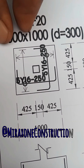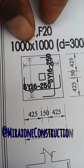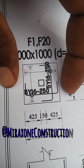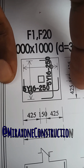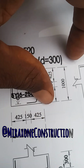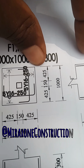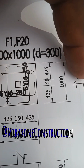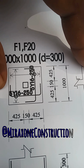As you can see, here 1000 by 1000 signifies 1 meter by 1 meter, so the sides of the column base are in square form. Here is 1 meter, here is 1 meter, here is 1 meter, here is 1 meter. D stands for the depth, the concrete depth of the column base, which is 300 millimeter. So it's equivalent to 1 foot.